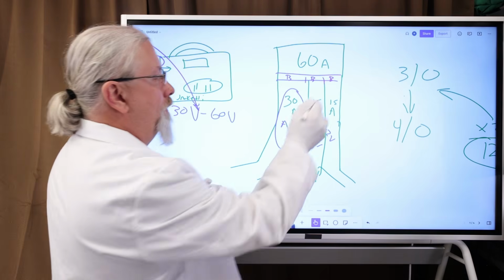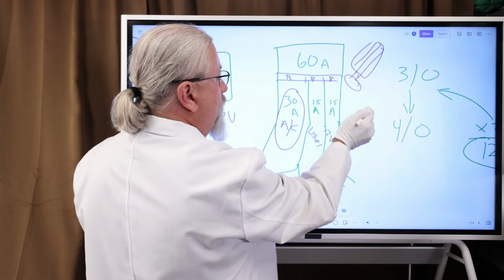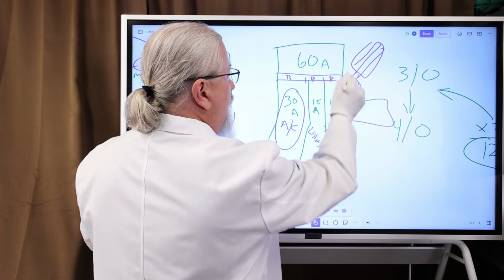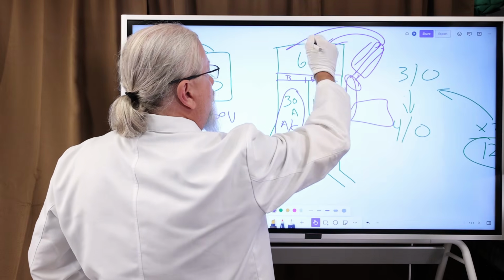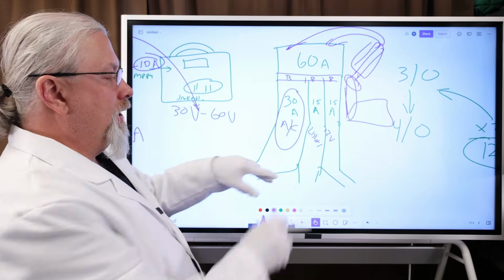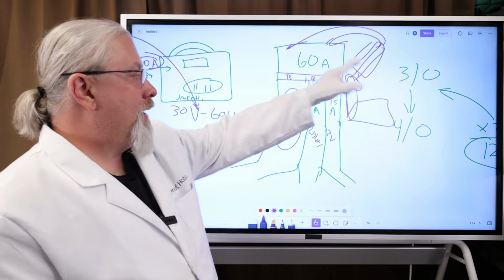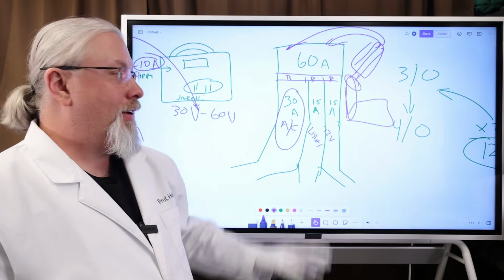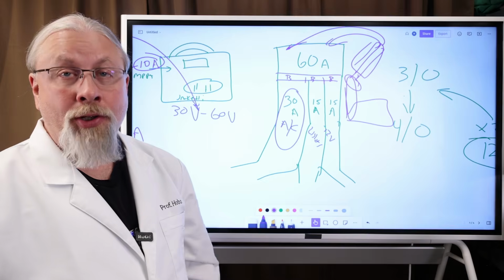That's going to be your alternator, right? Most cars nowadays got an alternator with a little wheel on it, which runs to the motor. The motor powers the alternator, which sends that power into the electrical box where it then splits out and goes to all your accessories in the car. In an RV, that might be a solar panel going in and doing that instead. In a home, that 60 amps is coming from your utility.